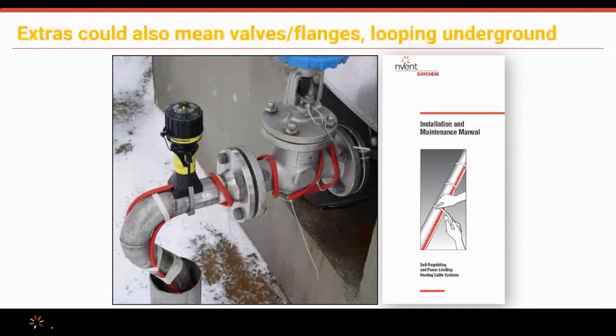So don't forget about those extras. I mean, 4 feet down, 4 feet back up, you've just added another 8 feet to your overall design. Now, the other extras that we want to make sure we're thinking about is any connections. For every connection, kit, end seal, T connection, we want to add an extra amount of footage. Depending on the application, you can be conservative or you can be short with your number. I usually add about 5 feet per connection. That gives the guys a couple oopses in the field if they need it, as well as safety factor.